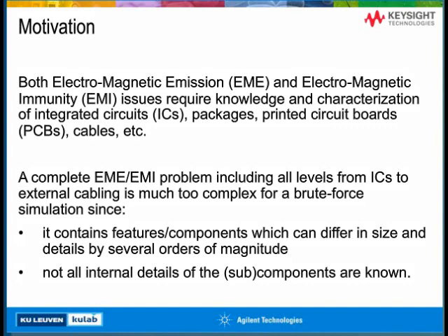What you can get quite often is behavioral models of the integrated circuit, which show you the input-output behavior. It's also true, for example, for connectors, from which you can get CAD designs, but which only have the mechanical and not all the electrical connections.